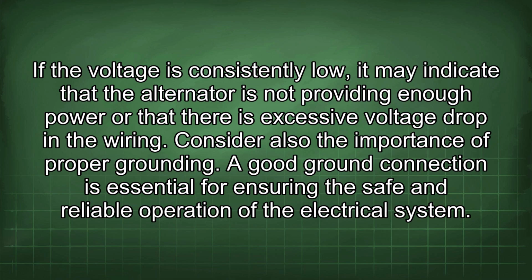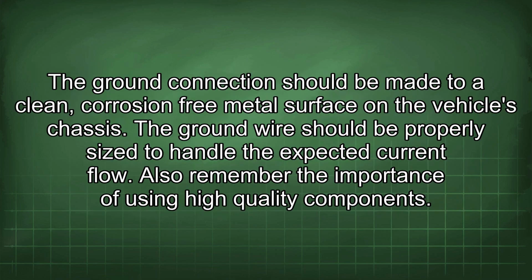Consider also the importance of proper grounding. A good ground connection is essential for ensuring the safe and reliable operation of the electrical system. The ground connection should be made to a clean, corrosion-free metal surface on the vehicle's chassis. The ground wire should be properly sized to handle the expected current flow.